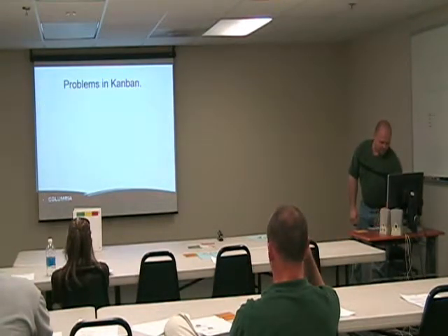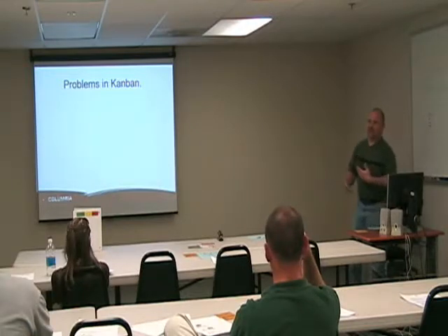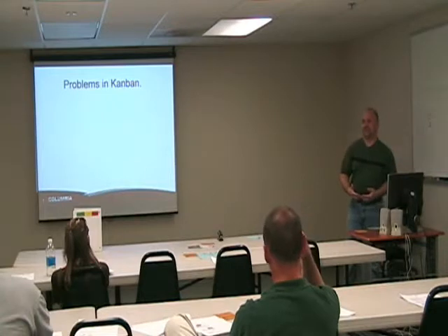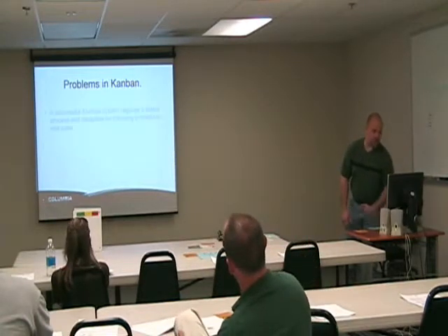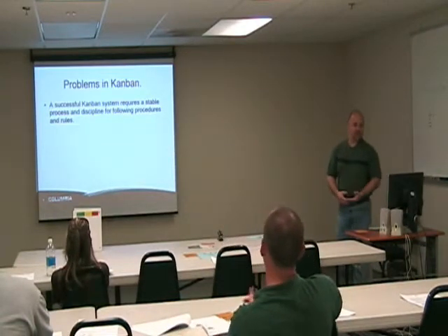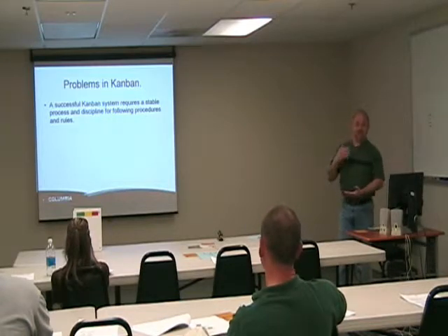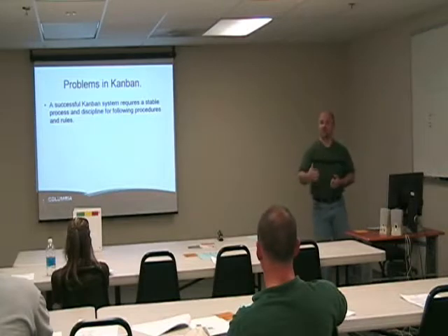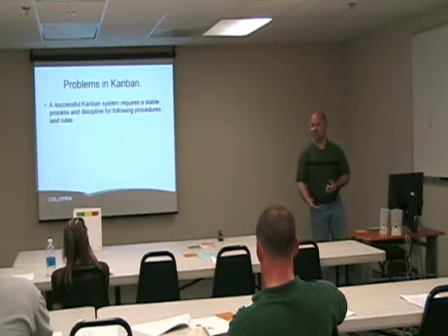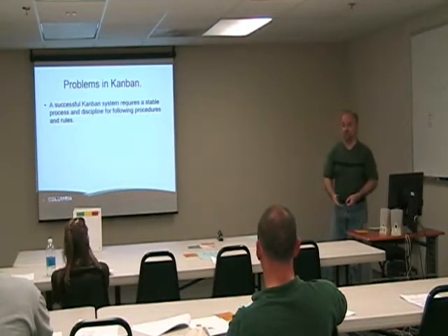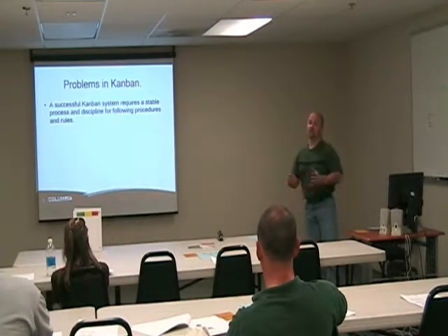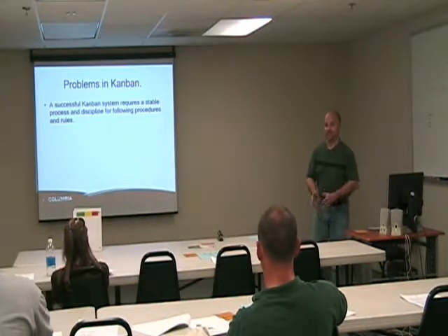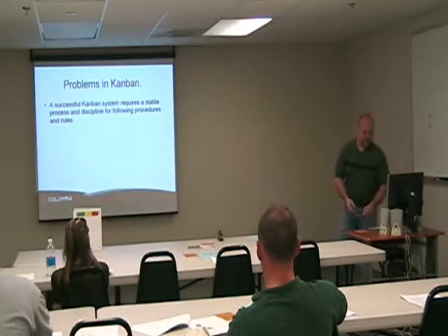Now, problems in Kanban, and it's almost requirements in Kanban because it's very finicky in how we use it. A successful Kanban system requires stable processes. It requires us to provide material into it consistently. We have to keep the screws coming in. We have to keep the glass coming in. We have to keep everything right when they need it there at that time. And I see a few eyebrows raised on that.